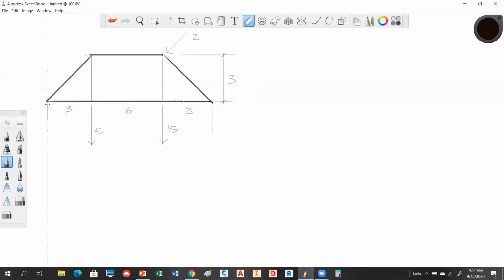So we're going to have one this direction, up or down, and the other one is going to be reacting left or right. So I'm going to put this like this. Okay. And I'm going to describe my convention over here. Up, to the right, and clockwise is going to be positive. All right, so this is the reaction at A and the reaction at B.